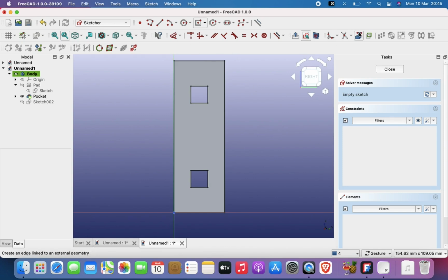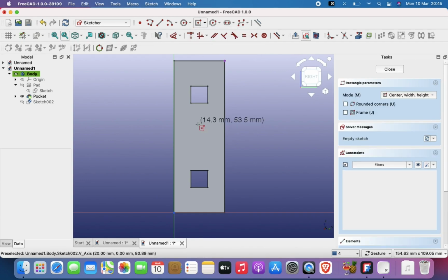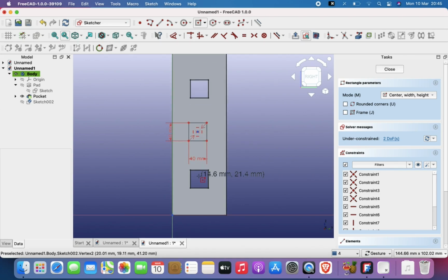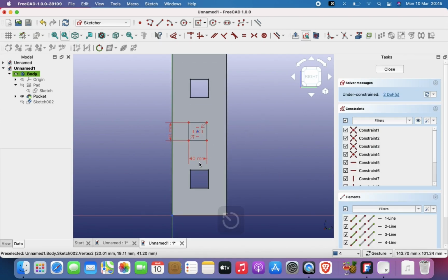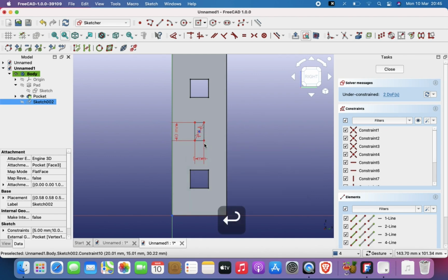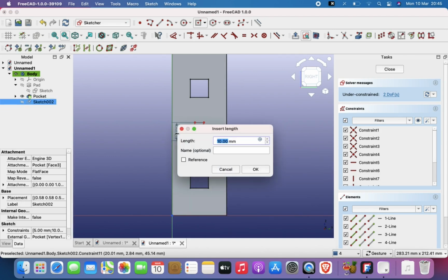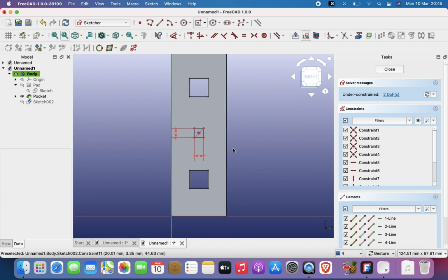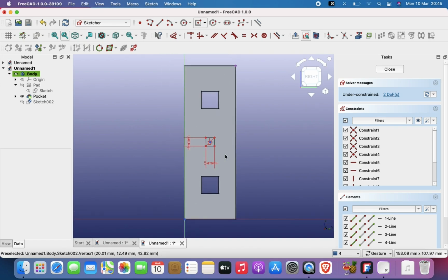So let me go to my project geometry tool, and then I'll select this point here. I'll press escape, then I'll go to my center point rectangle, and I'm just going to draw the rectangle, not minding where it is supposed to be. So that's also 10 by 10, or for the sake of making it different, escape, let's make it 5 millimeters by 5 millimeters. So that's a smaller rectangle there.